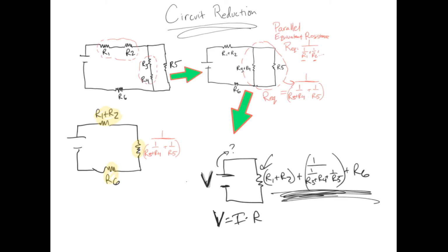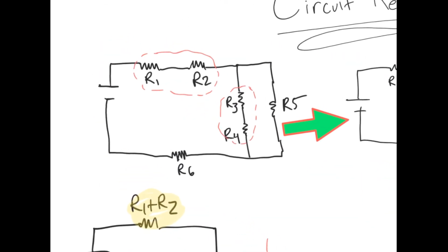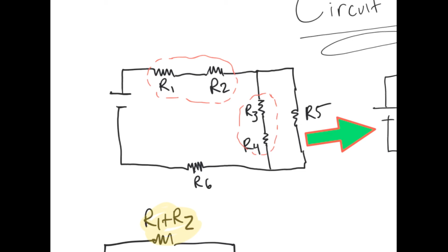So what we do with that, this last picture you have to remember is kind of an analogy. And once we know how much total current would be coming out, we actually go back to our original circuit, and we'd say, now that I know the amount of I coming out, I can know how much is going across each of these devices, and then we can split it up and see how much it goes into each branch. So we kind of have to go back to our original when we go to solve other things, and we'll practice more of that with the real scenario next.